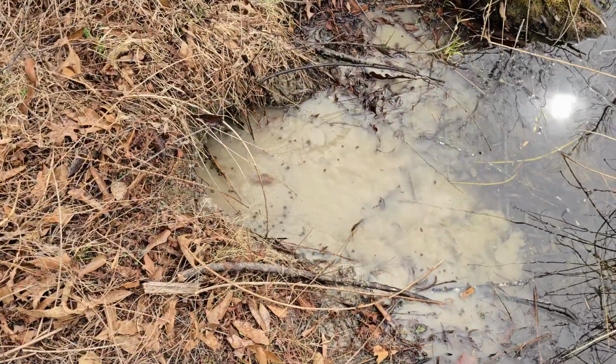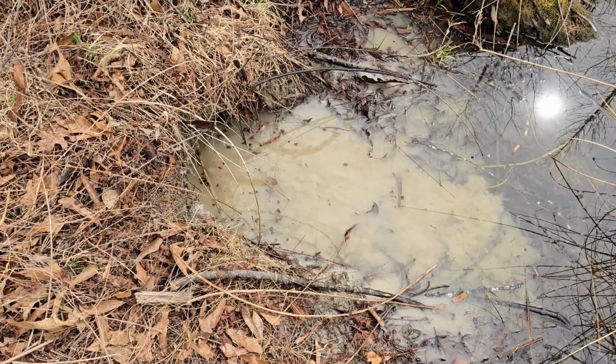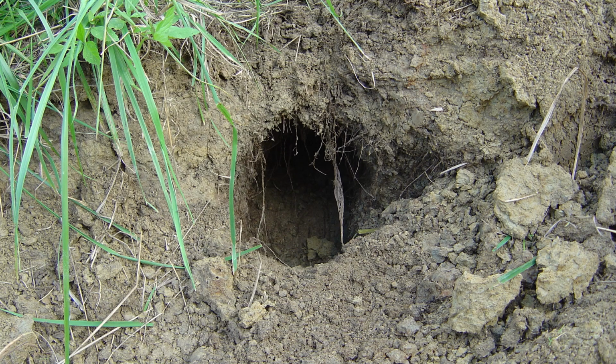The water is circling at the entrance of this burrow, so it's not draining the wetland at this time. To prevent the dam from failing, it is very important to use an excavator to expose each muskrat burrow and then to fill each burrow with clay that is compacted. Here's a muskrat hole in a dam as we began to dig it out.